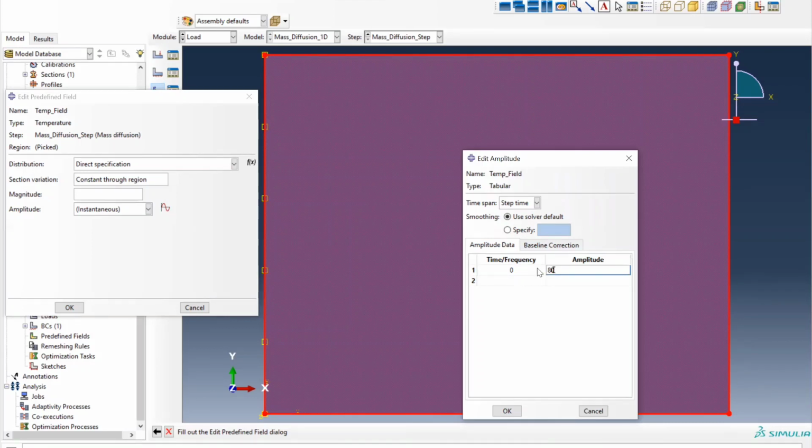So that's what we are doing now. We were saying that now it's the temperature 80. We're kind of telling Abaqus to relate that 80 to this value here. And now the time frequency, we're saying our value up to 2880, and this one here up to 160.